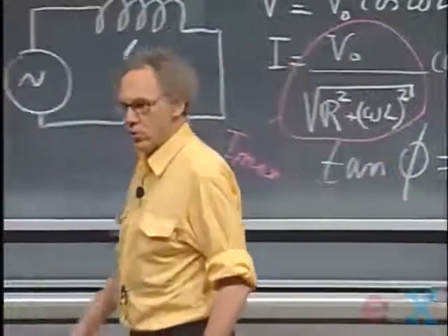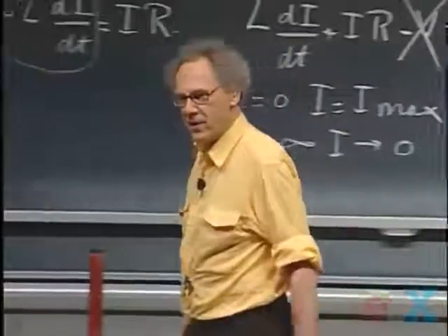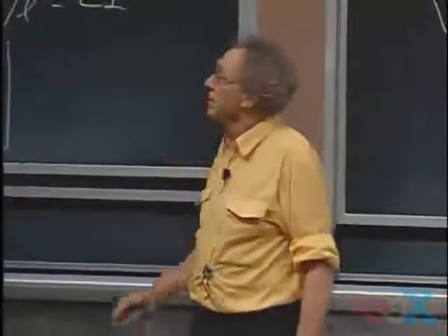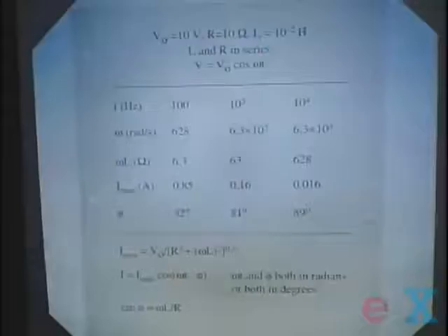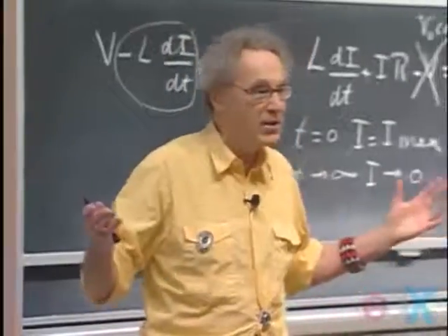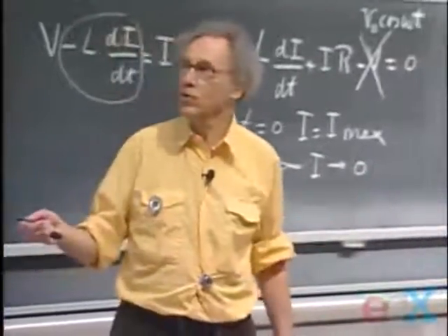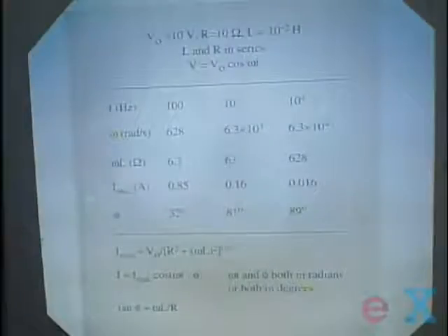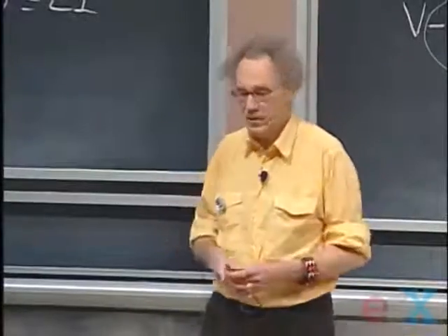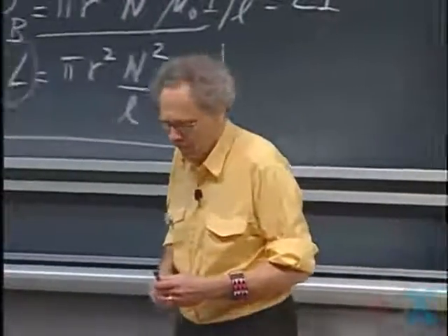I'm going to make you listen to music. And there will be violins which produce probably 3,000, 4,000, 5,000 hertz. And then I will turn on all of a sudden the 10 millihenry. So first I will make you listen to music whereby there is no 10 millihenry in there. And then I will turn on the 10 millihenry, and what you will hear, that the violins disappear. Because the current reduction is now huge on the high frequency, but is very little on the low frequency. And that's the idea of what a self-inductor can do for you.